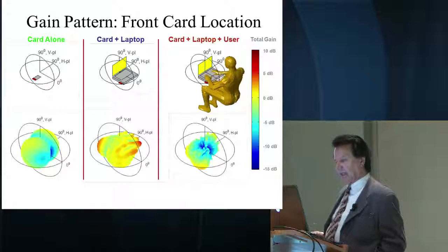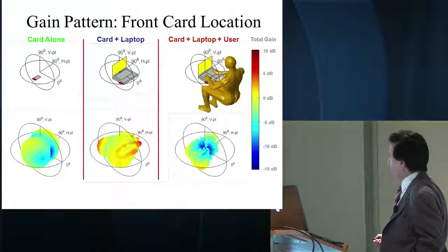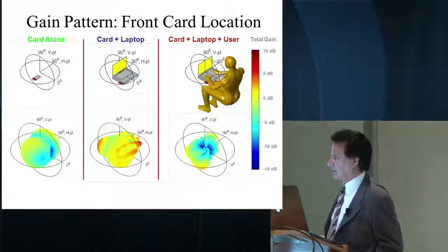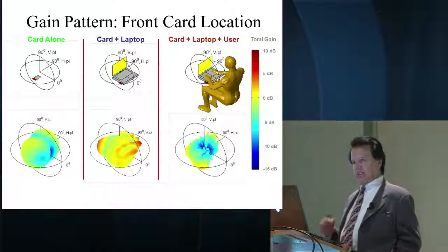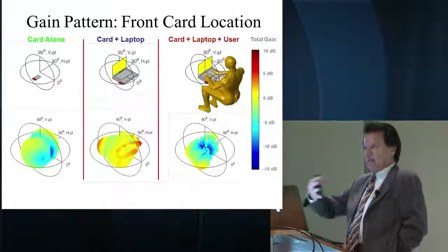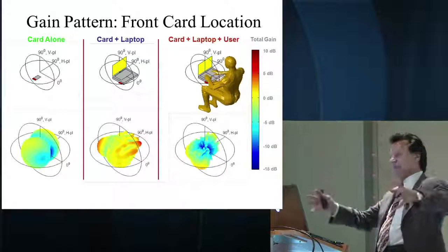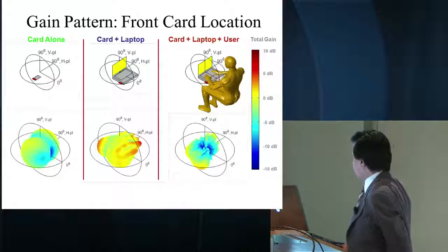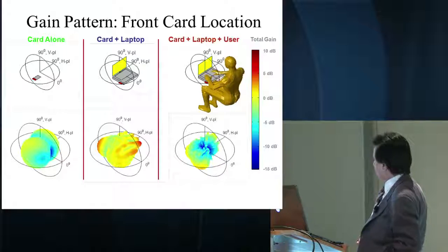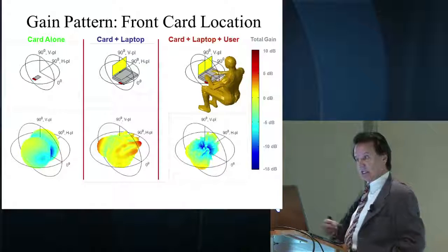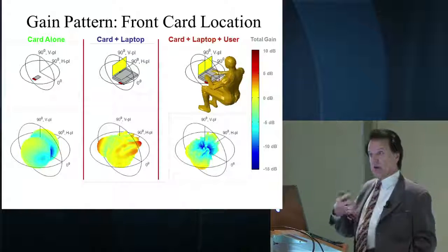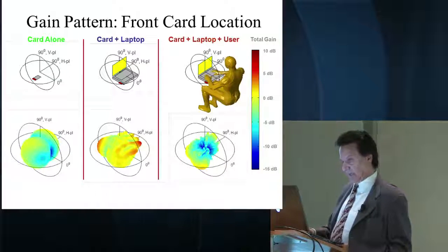Why is that? The reason is that when these antennas radiate, that radiation oscillates electrons in your body, and oscillating electrons, which essentially means time-varying current, radiate, so your body is part of the antenna, and then collectively, together, that's what defines the radiation pattern of this system. So clearly you can see in the back, due to the blockage of this human, you don't get much signal going to your antenna from the back direction. But now, these capabilities are available to understand what is going on.